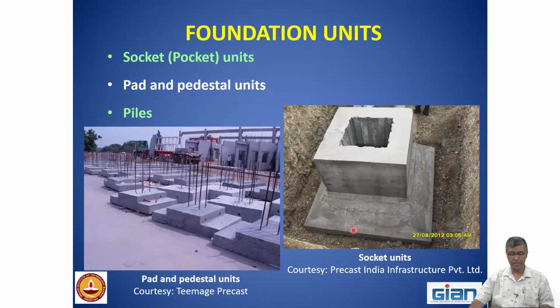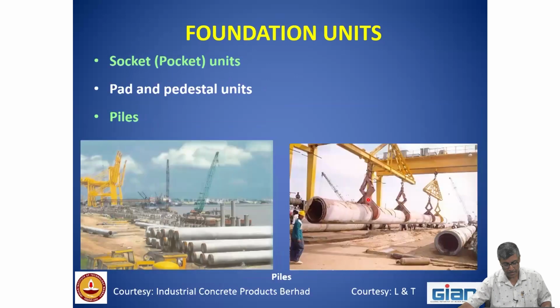Coming to the foundation units, I talked about this yesterday, that shallow foundations can be pad foundations, which can be used when I don't need fixity at the bottom, whereas if I need fixity at the bottom, then I should go for a pocket or socket foundation. And we also have the pipe. I talked about the beneficial effects of this pipe in a highly marine environment.